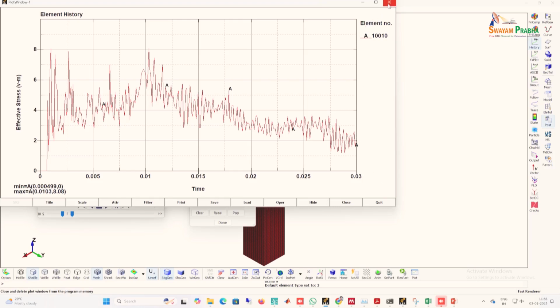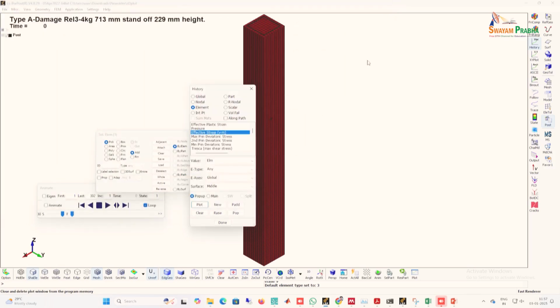And you can cross check. One good way to maybe start a model, if you're working, let's say, as he presented with UHPC, you might have stress strain curves. So you can model the cylinder, maybe the cylinder that he did, and then match the curves. Then you can adjust the parameters to match the curves, and you can use that. That's one way I've used for high strength concrete.